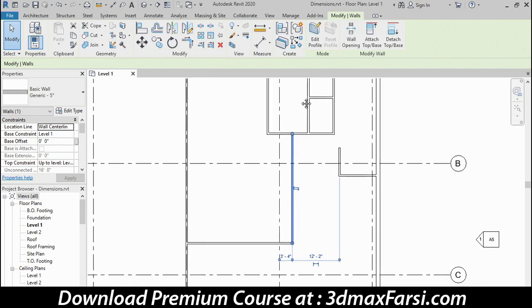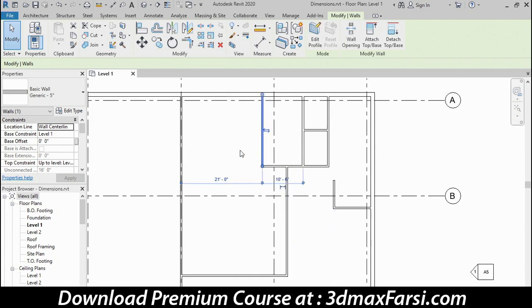So I'll pan down slightly, select this wall next, and if I'm satisfied with where the temporary dimensions are, I can edit them directly, but in this case, I want to measure this wall off of this wall. So once again, I could take this witness line grip, drag it, notice it will highlight that wall, I'll let go, I'll click right on that number, and this time I want to do 4 foot 8 inches. Well, another way that I can do feet and inches is to put in the number of feet, followed by the foot symbol, which is the single quote mark, and then the number of inches, and press enter. Now, both of them achieve the same thing, so it's entirely up to you which method you use.